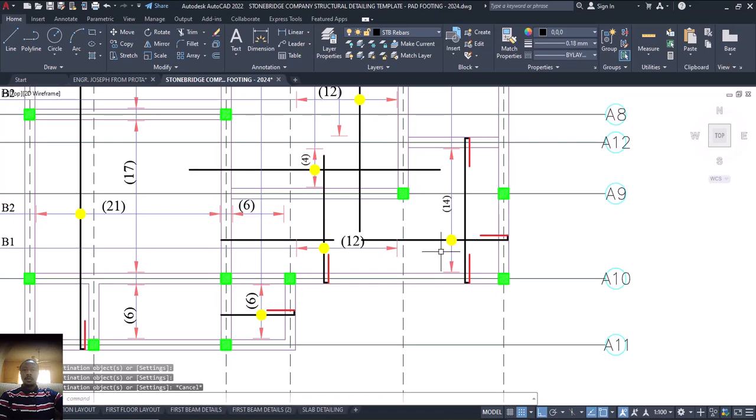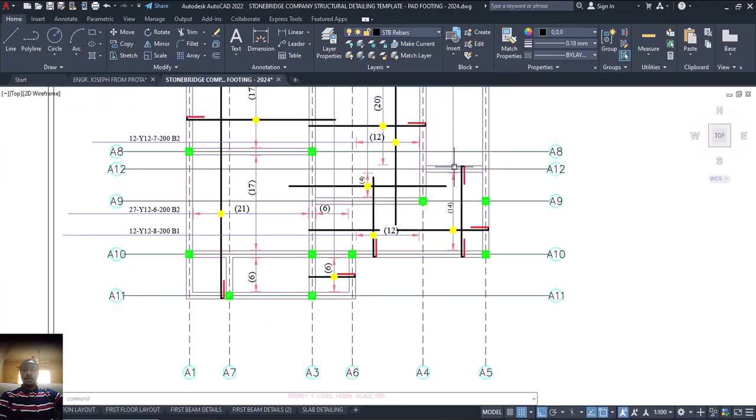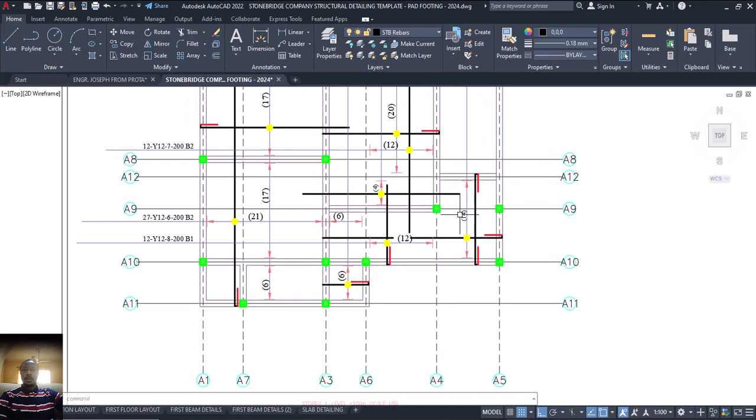How is this one going to run? It's going to run from here to this place. Is that okay? It's going to run from here to this place. Is that okay? Why I'm doing this is because of the return bar here. There's going to be a return bar here. If you use this one, it then means at this point no return bar. But an engineer who knows what he is doing should know that here there's a return bar. Is that okay? But for the sake of, we don't know the person that's going to handle the project, since we are not the one that's going to handle the project, that's why I want to do this. Is that okay? So that is that.